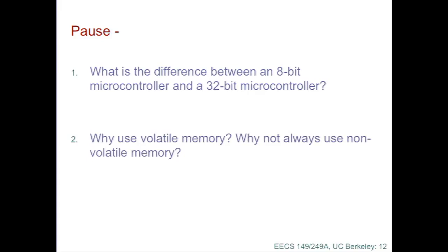Yeah. Talking about the width of the data bus, are you talking explicitly about the width of the data bus or the width of the ALU as well? Because some processors do funny tricks. You know, like normally it prefers to work on 8-bit, but you can double pump it, and the ALU can handle 16-bit. Yeah, that's a very good point. And any reduction to one word of something as complex as this is going to leave out a lot of detail, right? So if you hear that it's an 8-bit microcontroller, that tells you something, but not a whole lot, right?